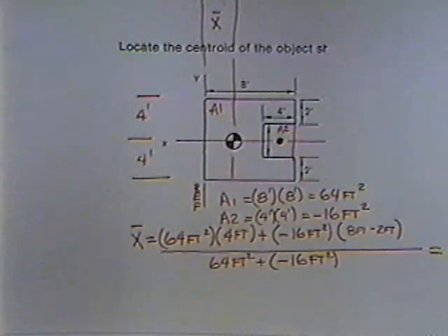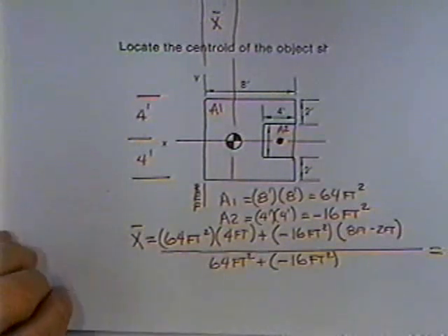Incidentally, that's where you would want to place the equivalent uniform force underneath the footing so that you'd get uniform pressure underneath that footing. If you cause the soil pressures to act through the centroid, then the stresses underneath that will be uniformly distributed.